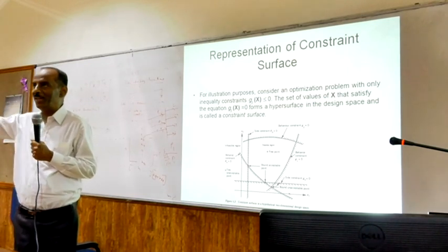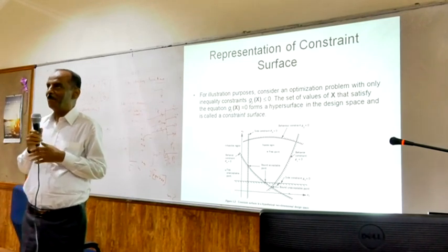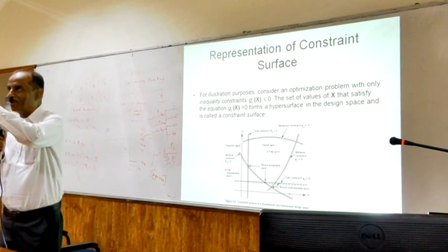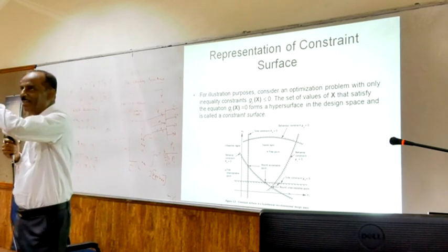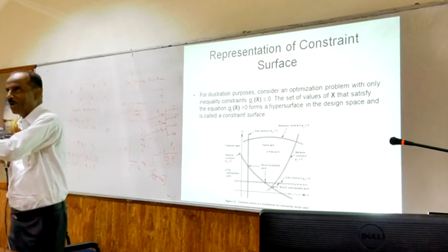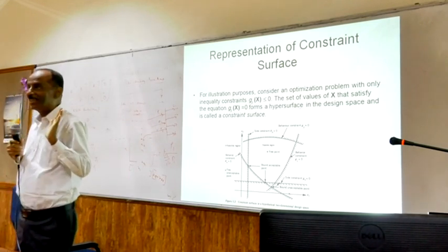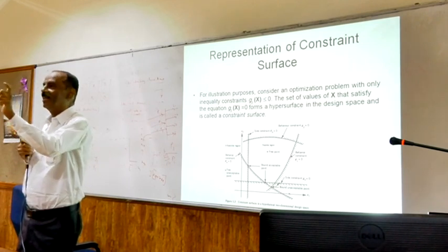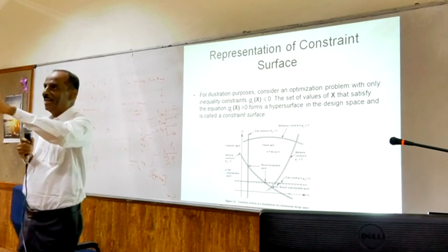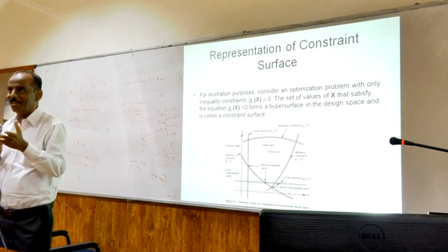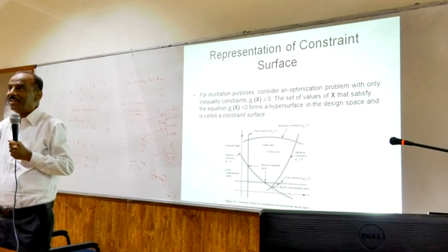I agree, magnitude varies actually. But you are not able to give the correct answer. See, the variation of the voltage is going on. Similarly, current variation is also going on. But the current variation is lagging by 5 milliseconds. That's all. 90 degrees means, sorry, one cycle how much? 50 cycles means 1 by 50, 20 milliseconds. 90 degrees means 5 milliseconds. Am I correct? So, since it is varying with 5 milliseconds, after the voltage reaches max